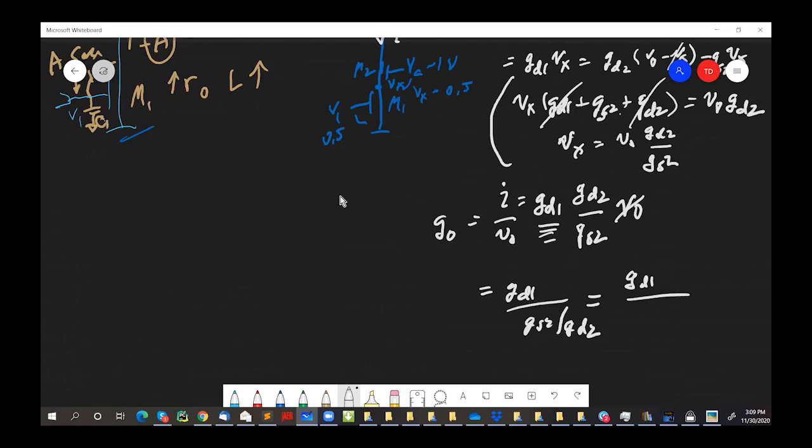Well, remember, it's just the ratio of the early voltage to the thermal voltage, right? Do you remember that? Is that clear to everybody? Yes. Okay, so the output conductance is actually the original output conductance, but divided by this huge ratio.